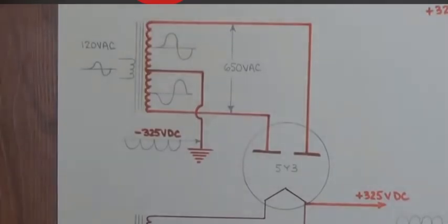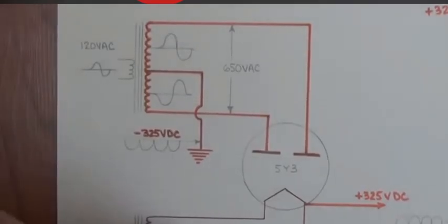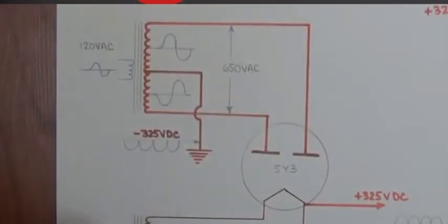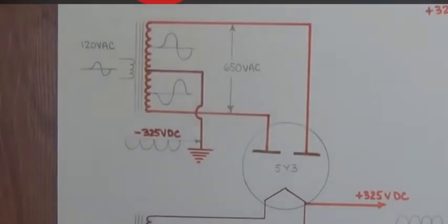Now let's look at our second little bite-sized piece, and that is the 5-volt AC circuit. Remember, it was right up here at the top in our Champ schematic. Now, first off, let's look at what the winding ratio must be to drop 120 volts AC to 5 volts AC. Did anybody come up with 24 to 1? Okay, so there must be 24 windings on the left for every 1 on the right, so that when we run 120 volts AC through the coil on this side, we end up with 5 volts AC on the right side, or the secondary.